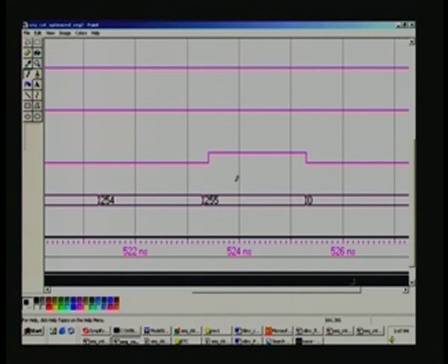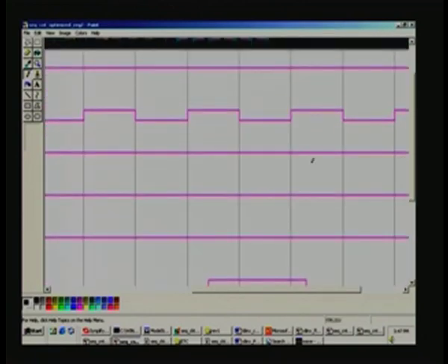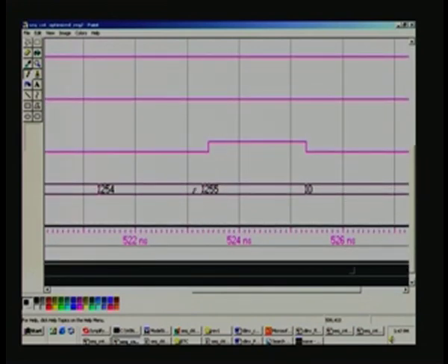Notice the delay here also: when 255 has occurred, only after a slight delay, this happens because it is being compared. Similarly here, when you go onto the clock, the rising edge is here, and 255 itself maintains the same phase shift. In this fashion you can analyze any other circuitry that we have seen before, or create your own design and analyze.